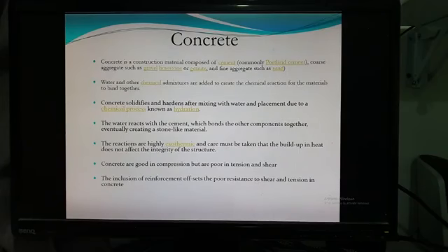Okay, so this depends on the grade of the concrete and also the amount of concrete you are using. And we want to control the exothermic process so that the heat that is generated will not compromise the strength of the concrete. So that's why you can see that when people do concreting, especially on small jobs, they would put a bit of a covering over the surface of the concrete, like some wet rags.